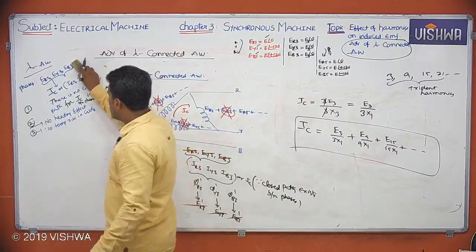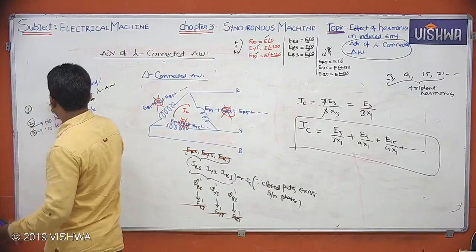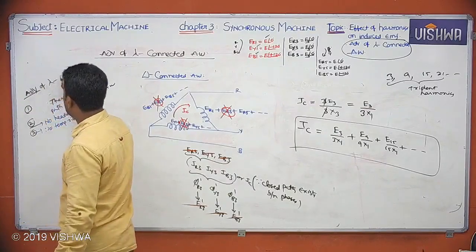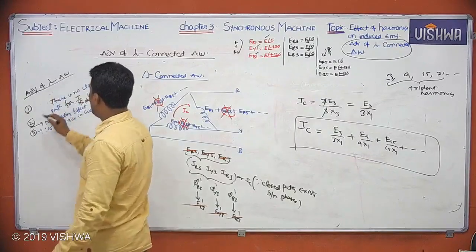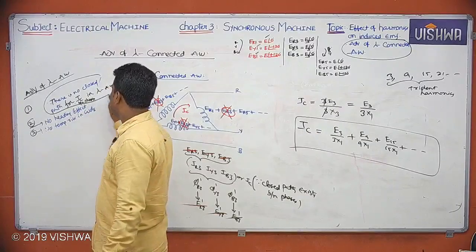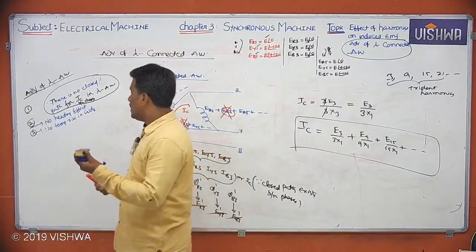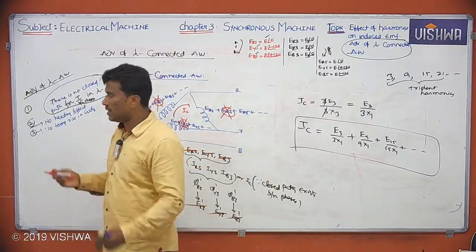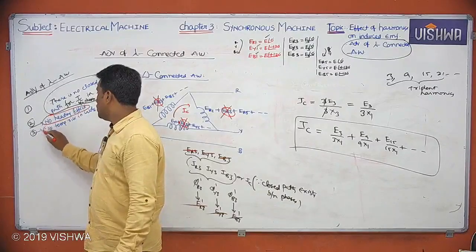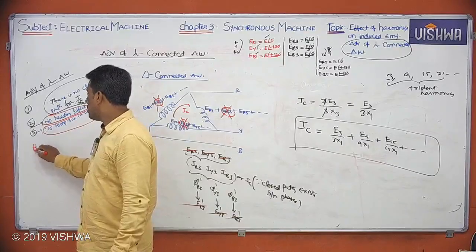Okay. Next one, tell me what is the one more advantage. These are the advantages of star connected armature winding. Number one, no closure path for circulating currents between phases in star connected armature winding. Number two, no heating effect because there is no path of circulating currents. Number three, no temperature rise in winding. Okay. Number four, what is that?